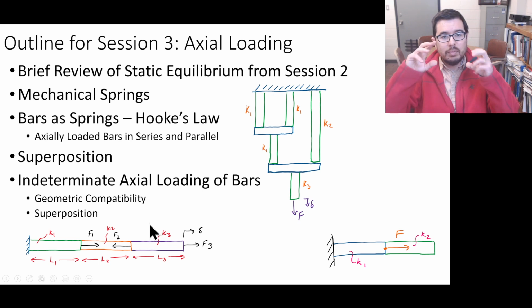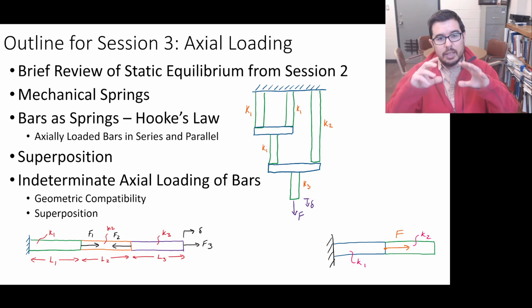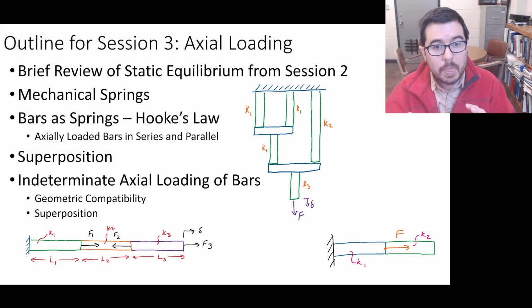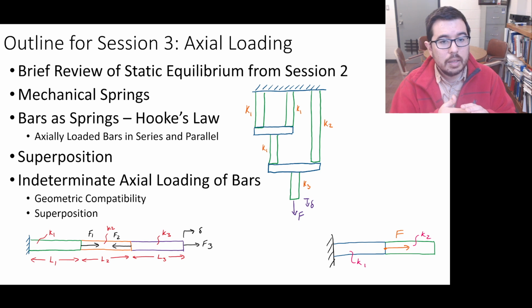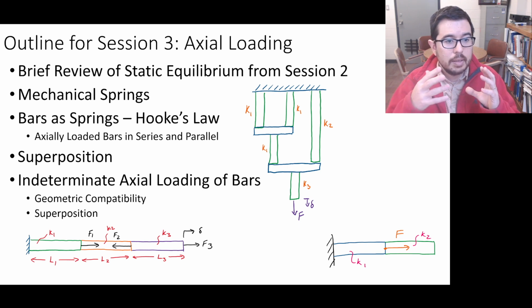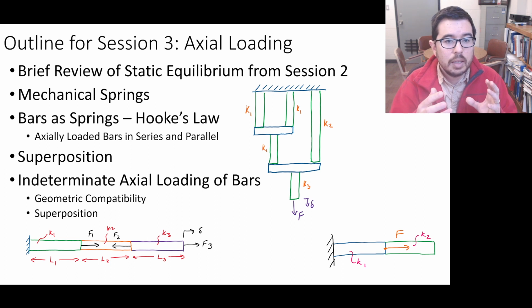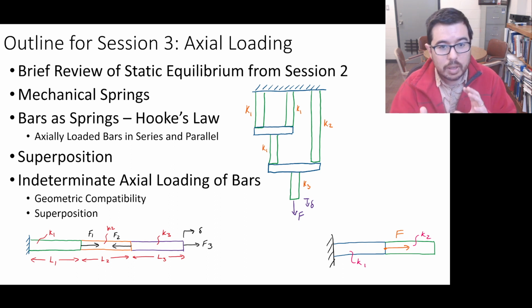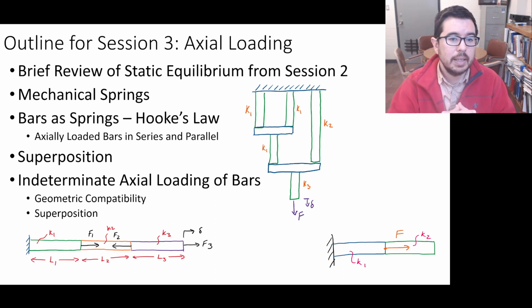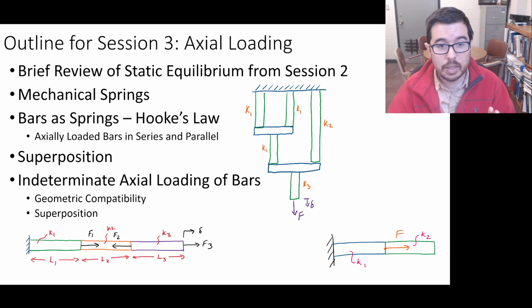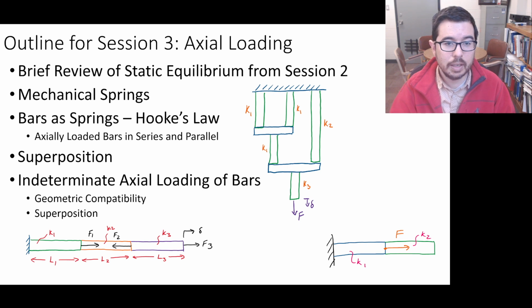Hopefully, the ideas of using method of sections and the relationships for springs are now more clear and allow us to be able to solve more problems, specifically the indeterminate ones that aren't solvable just using static equilibrium.